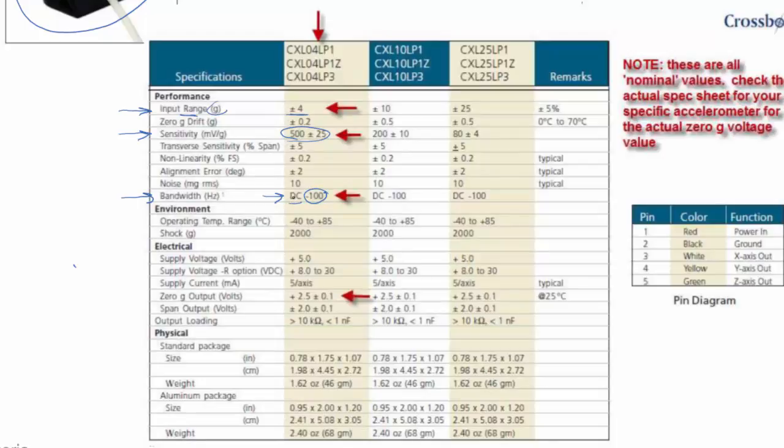So when you see an accelerometer that has DC, it means you can measure constant acceleration also. What does that mean? It means that it can basically see G, right? It'll respond to the Earth's constant acceleration, for example. And you'll see changes in voltage when you excite it with the constant acceleration from Earth's gravitational field.